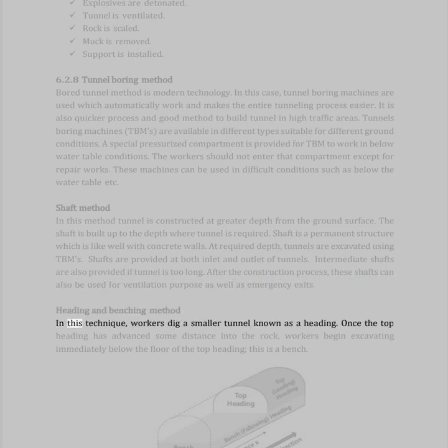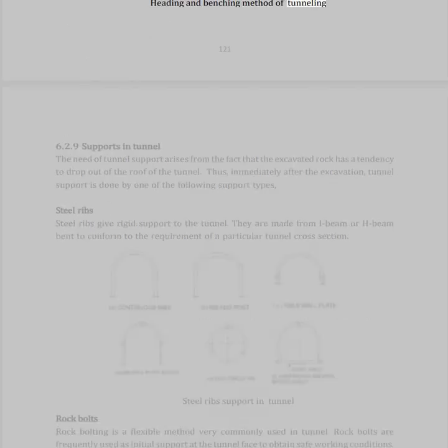Heading and benching method. In this technique, workers dig a smaller tunnel known as a heading. Once the top heading has advanced some distance into the rock, workers begin excavating immediately below the floor of the top heading. This is a bench. Heading and benching method of tunneling.